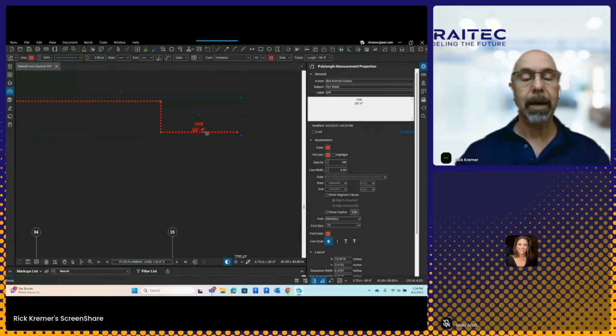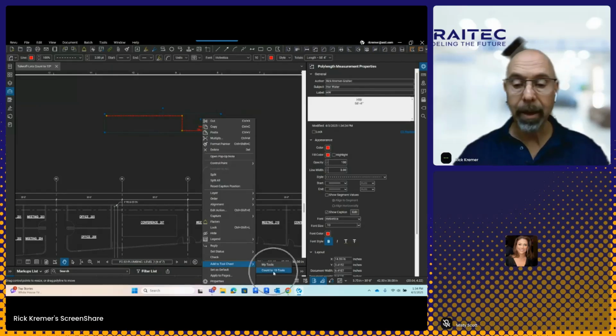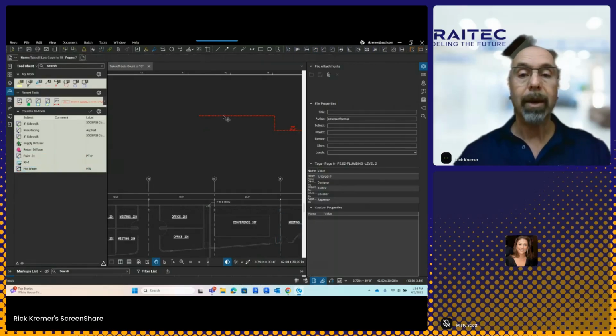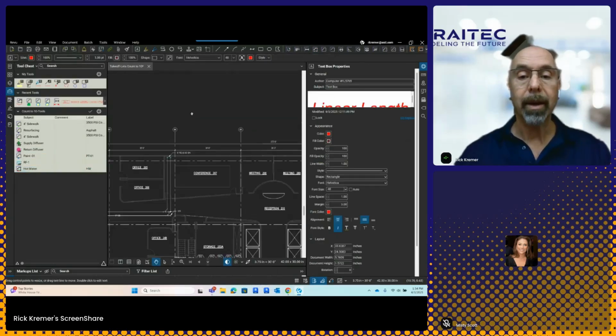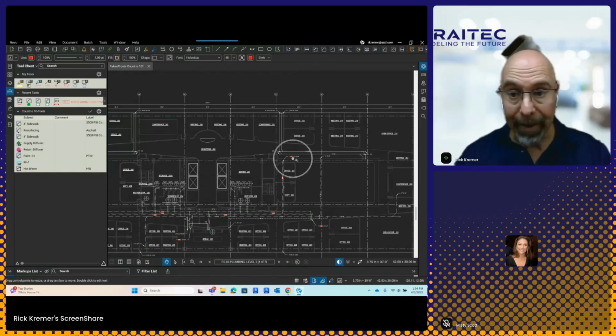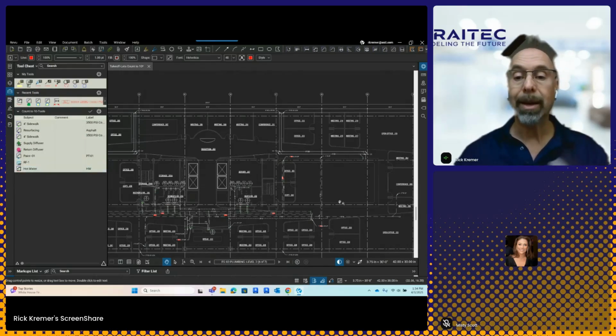All right. Now, I'm going to add this to my tool chest by right-clicking and adding that to the tool chest, double-clicking on it. So now I can use this over and over again. All right, so now with that information in mind, I've highlighted the information. Over here, hot water, right? Pro tip, over here under My Tools, I'm going to use a shortcut key so I can easily start to trace this.